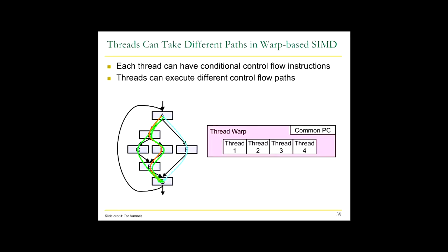So this is the problem with grouping threads, right? As long as it's sequential, they all go through the same program counter sequence. But once you have control flow, you have this problem that the threads that are grouped together are diverging from each other. This is called branch divergence. And this is why GPUs are not very good at irregular code. This is called irregular code.